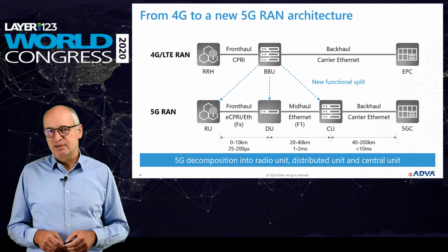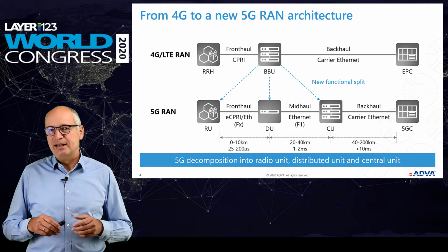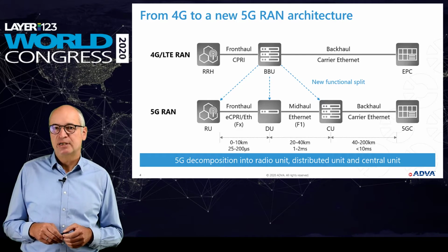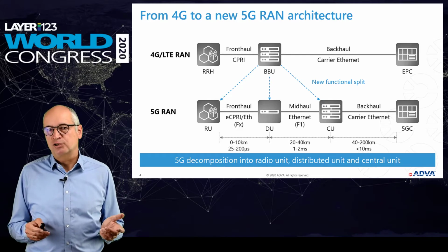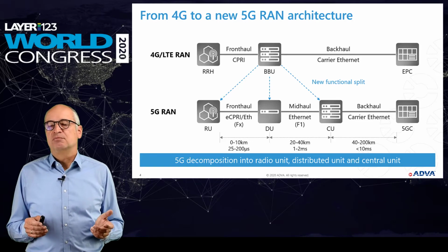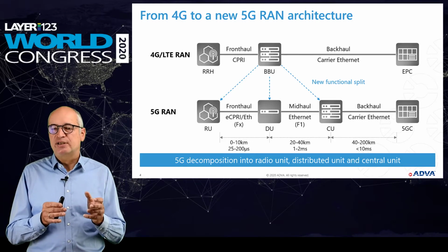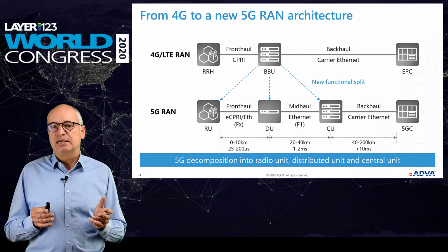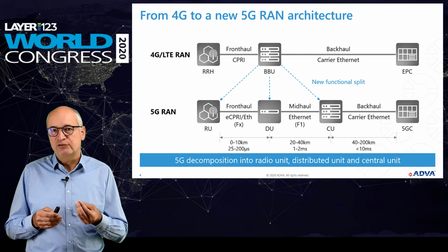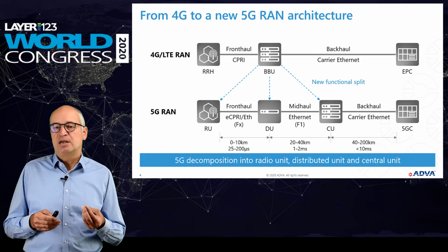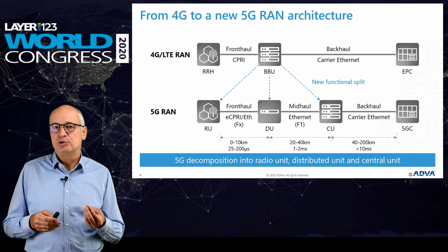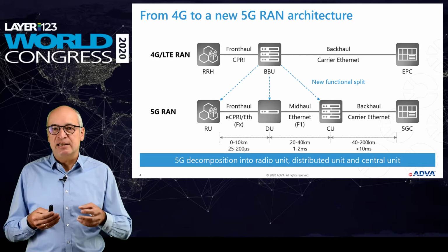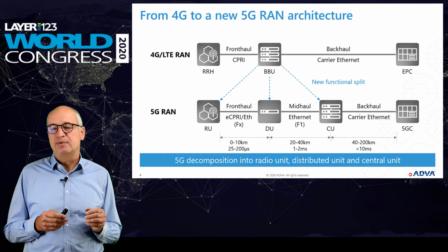Before going into the more details of the connectivity network, some architectural considerations which are relevant for the design of the connectivity network. You heard about front haul. Front haul, the approach that the legacy way of building radio base stations with quite complex functionality, the complete creation of the complex radio frequency signal from a user data flow in combination with the processing control protocols has been done in a BBU broadband unit within a radio base station.